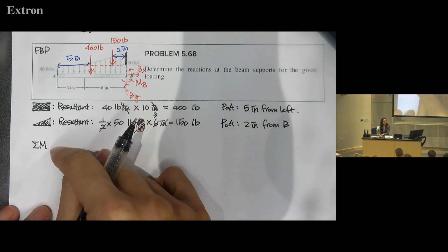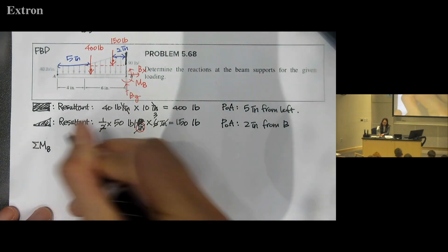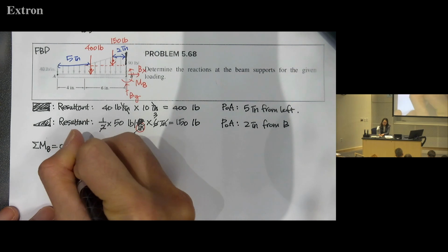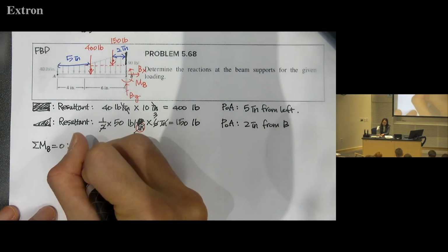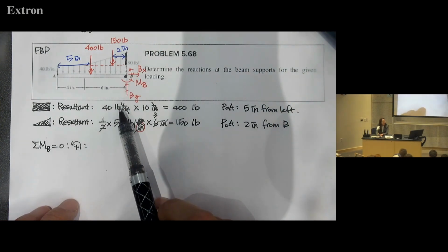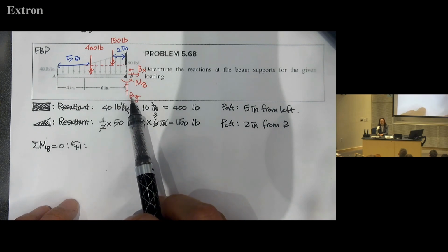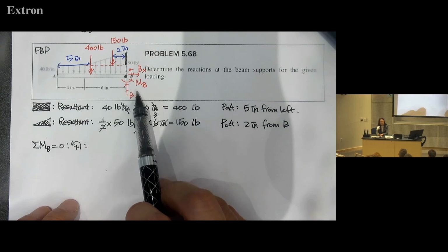So the reference point, you can use any point, A or center or B, but I recommend using B to eliminate other unknown reactions. And then assuming one side as positive, let's count all the moments together. So your moment by By, By times 0. Okay, moment times Bx, Bx times 0. And then moment from MB,